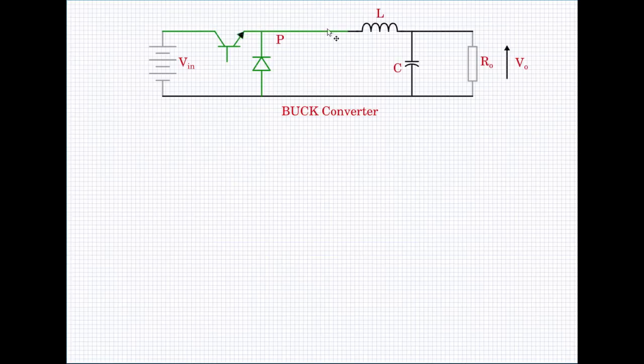The current waveform of the inductor is very critical, because this current gives information about the current flowing in the input, and therefore the current flowing in the transistor and the diode, because the freewheeling current also flows through the inductor. The current flowing through the inductor also divides into the capacitor current and the current through the load.